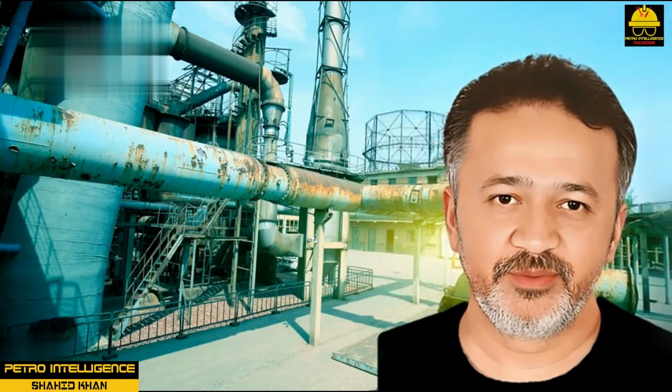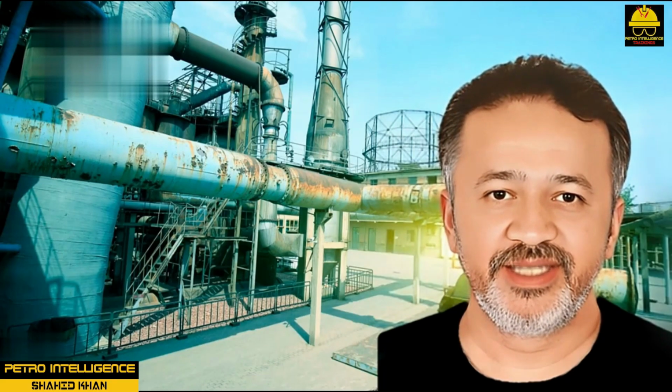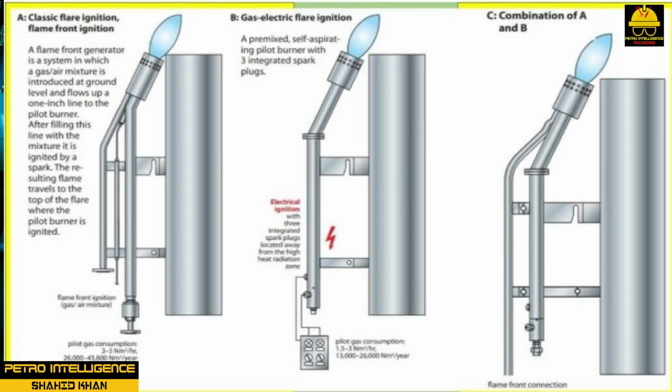Flare stack and flare pilots. The flare stack provides an elevated location for combustion in the flare tip. Flare stack elevation is selected to limit radiation heat at ground level. The tip is designed to allow smokeless flare operation at low discharge flow rates. Some flare systems are designed to handle only partial system or equipment failures without smoking. The steam flow to the flare is automatically controlled on the basis of the flow rate of gas to the flare. The flare pilots operate on natural gas and air ignited by a flame front generator.